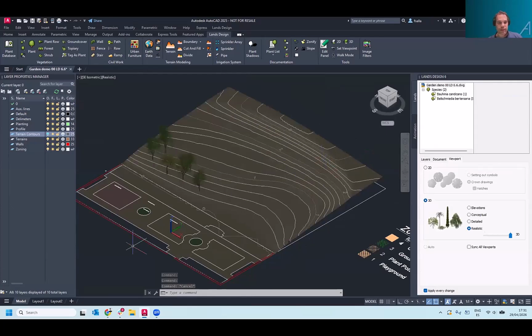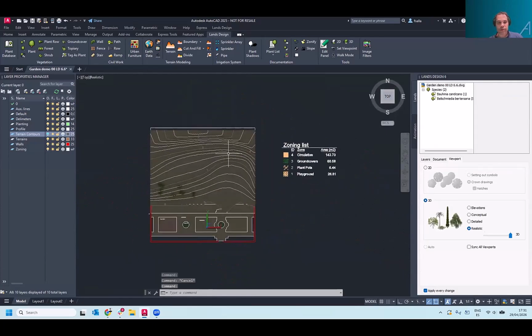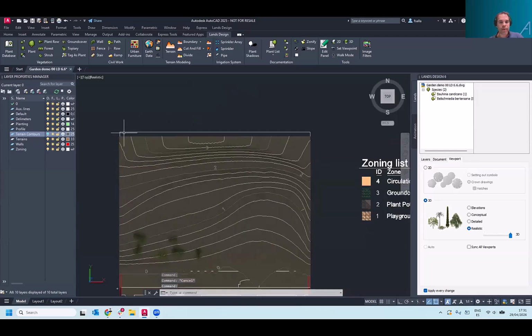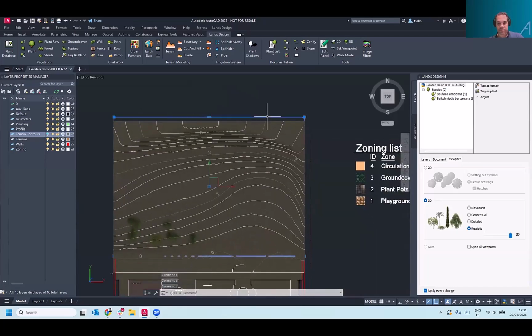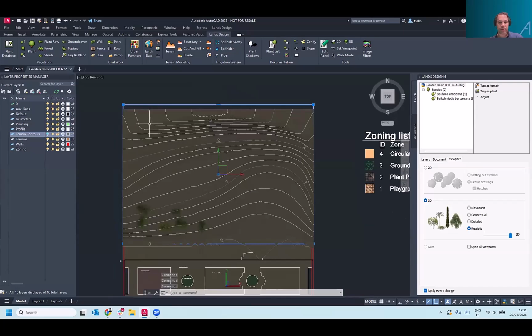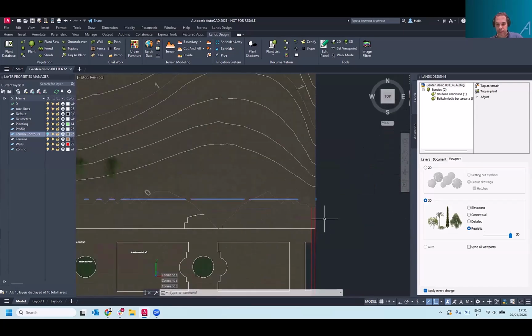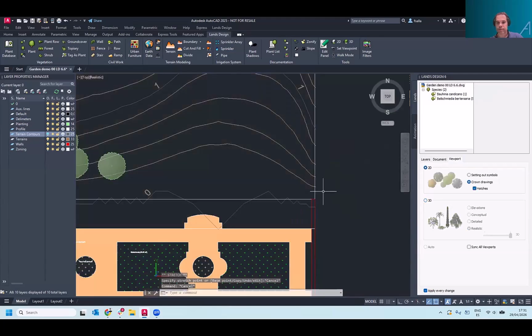Something else that we can do, if we see this terrain from the top viewport, we can see that there is a gap here. And we have this boundary curve, and I will use it to define the new boundary of the terrain. Actually, I need to adjust this curve so it meets. I will do this in 2D representation. It's always better, or I can do this afterwards.